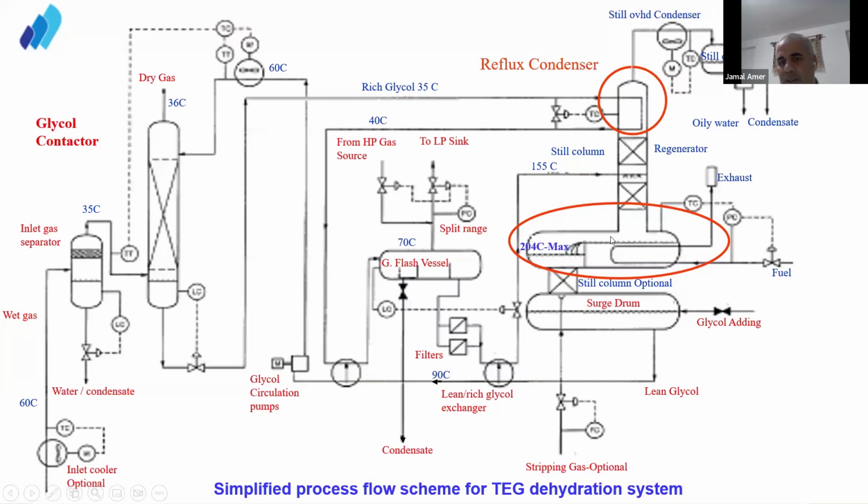We then don't have glycol to absorb the heat. So here we have a dangerous situation: if it continues for a long time, the fire tube could rupture or deform, and hot spotting will form. Certainly, a hot spot will be formed on this wall of the fire tube.